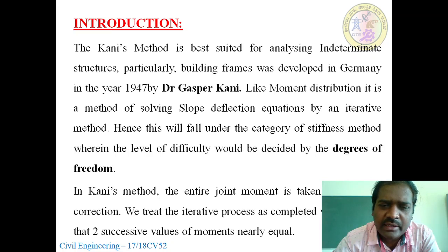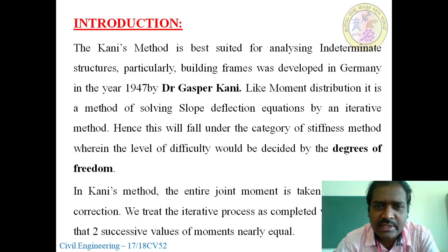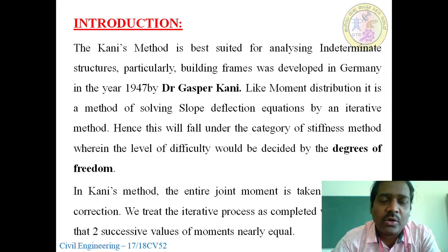We treat the iterative process as completed when we find two successive values of moments nearly equal, meaning in the fourth or fifth iteration. The previous iteration will be the same or nearly the same as the final iteration. So we will consider that final value as the contributional moment.